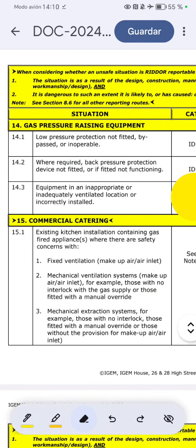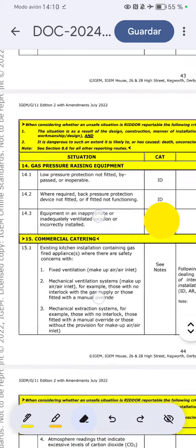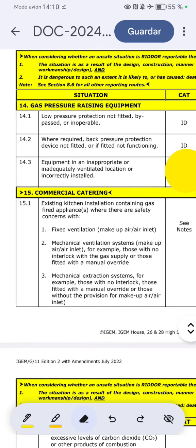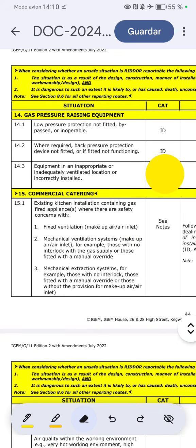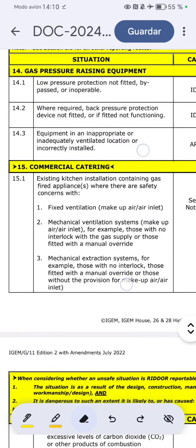Okay, it sounds like pressure is an issue with this. 14.3. Equipment in an inappropriate or inadequately ventilated location or incorrectly installed. ID with LPG or at risk? With LPG needs ventilation. So it's at risk. I would have said probably ID, but...